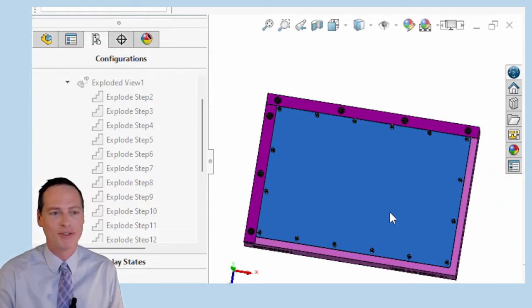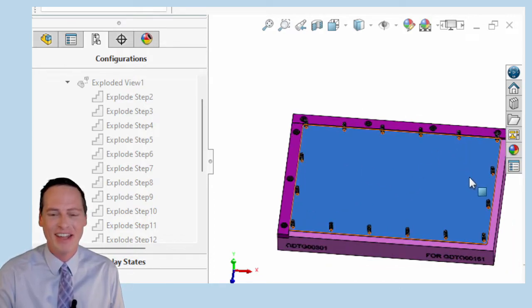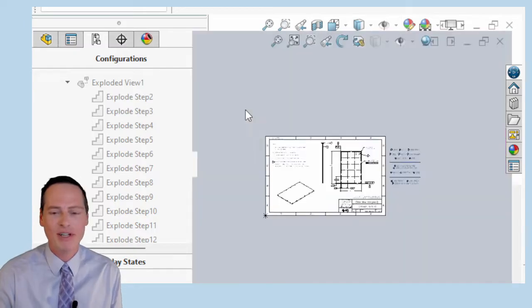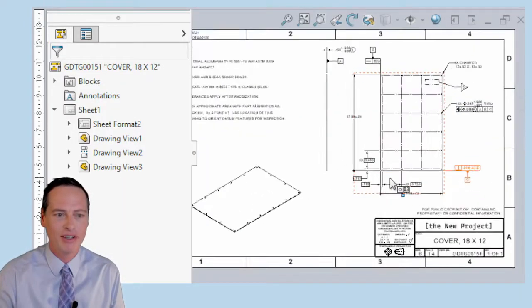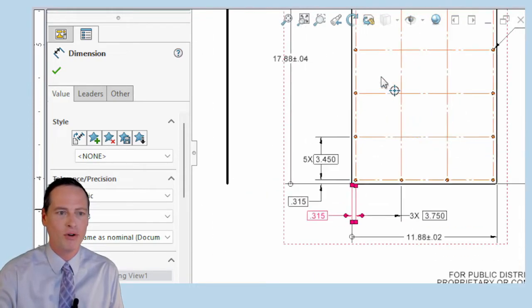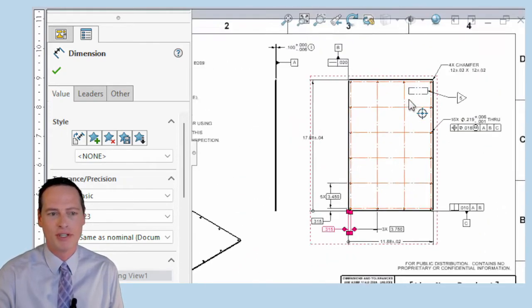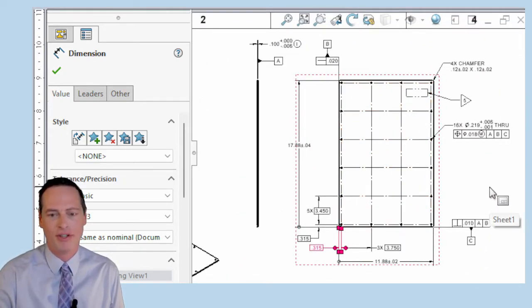So we have this datum reference frame that we've simulated with the fixture. It's important to know that when you dimension a hole as being a certain distance off the edge of the part, off of that datum feature, you're not saying to measure each of these holes from the middle of the hole to the local edge, with some calipers or something. No. You're measuring the position of those holes with regard to the datum simulator.